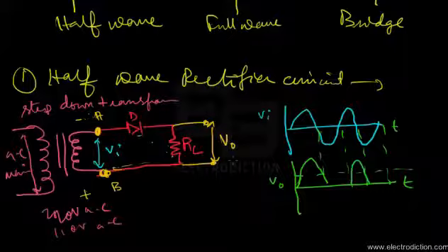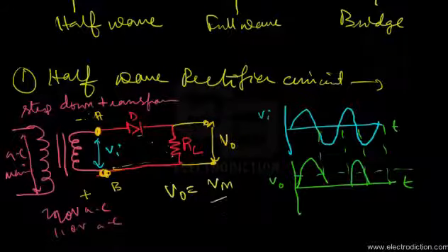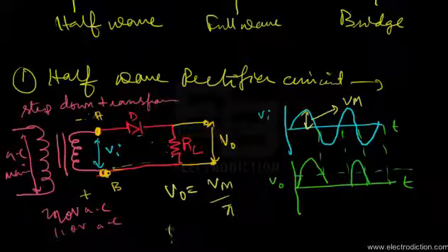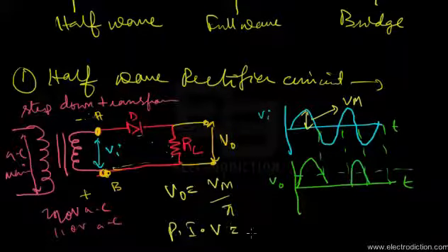So now based on this, we know what happens in case of a rectifier circuit. And now let me give you the mathematical expressions that are required in order to calculate the output DC voltage, which is of course Vm by pi, where Vm is the peak voltage of the input AC signal, as I told you. And when the diode D gets reverse biased, then the magnitude of input voltage Vi occurring across the diode gives you the PIV, or the peak inverse voltage, which is of course Vm in this case.